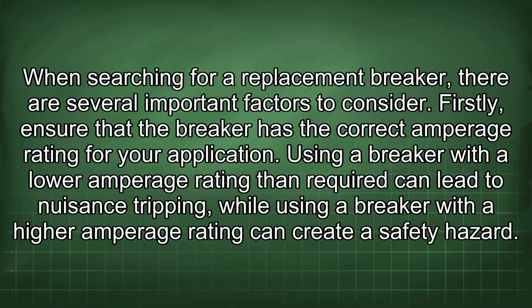When searching for a replacement breaker, there are several important factors to consider. Firstly, ensure that the breaker has the correct amperage rating for your application. Using a breaker with a lower amperage rating than required can lead to nuisance tripping, while using a breaker with a higher amperage rating can create a safety hazard.